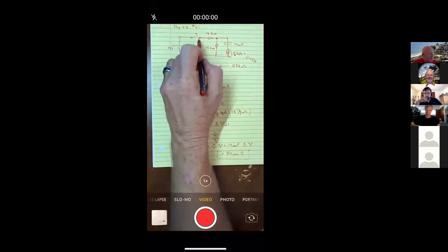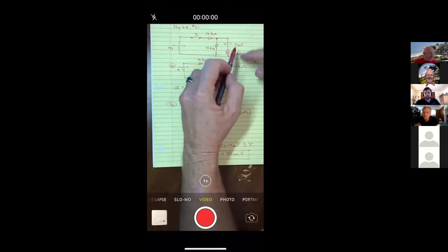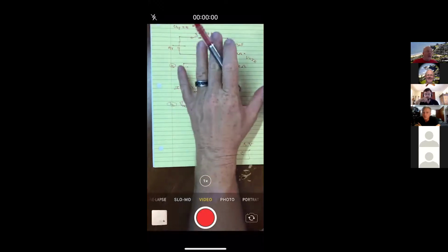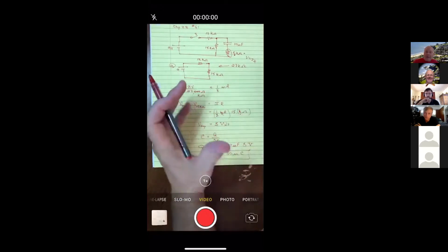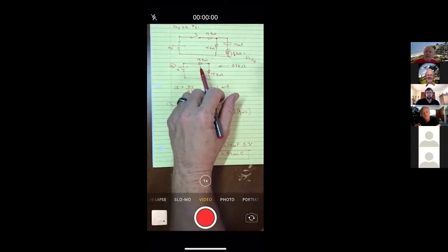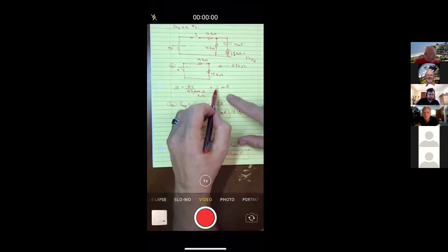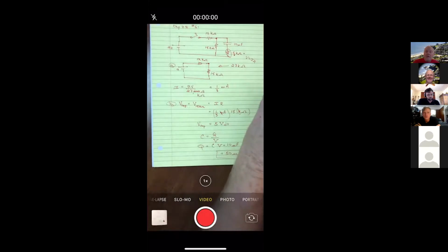So when you first close this switch, the current would come across the top, and some would go this way and some would go this way. And this would be filling up, and it would get less and less, and the current would be transitioning. During that time, we would call it a transitional current. And then after a period of time, it's steady state current. It reaches some constant value, which apparently is 1/3 of a milliamp here and 0 in here. So that would be the steady state. Transient, as the name implies, would be a value that would be changing a little bit with time. So transient is basically the same as transitioning. Yeah, it's changing, variable, in other words.